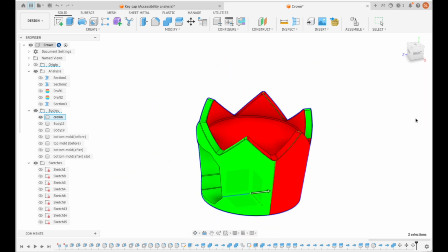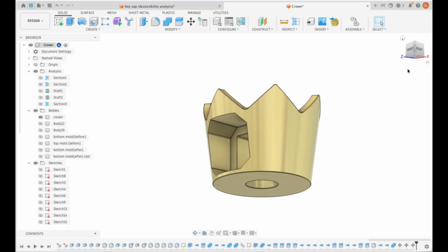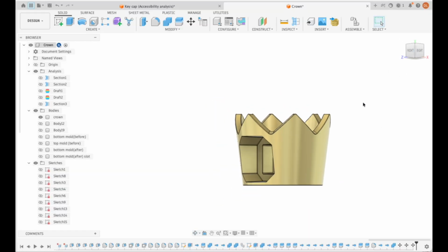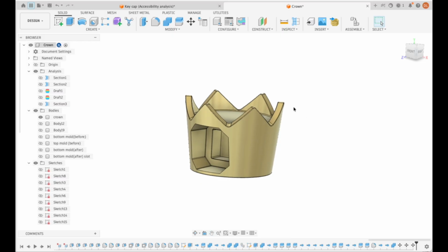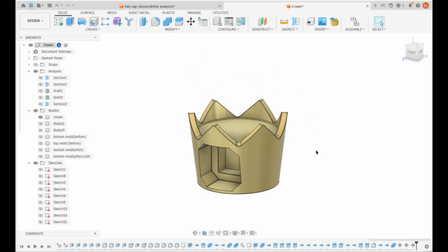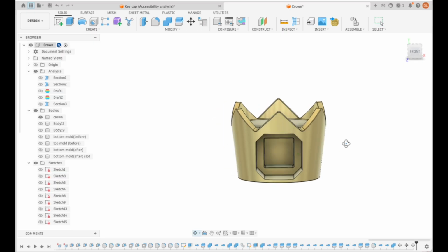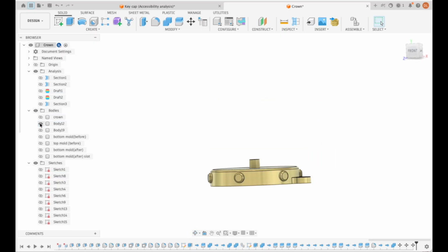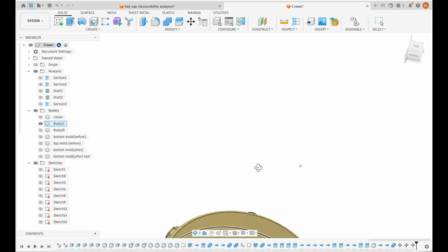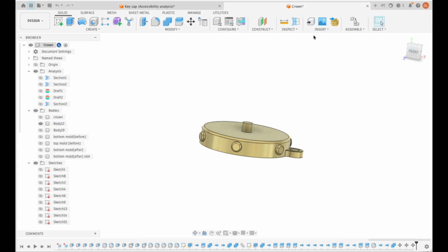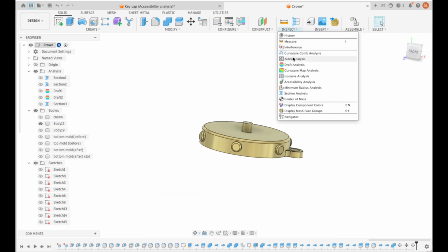This part inherently needs basically a 3-part mold, which will increase the manufacturing costs. So it might be better to improve this design for injection molding to remove the part or mold needed to produce this part, because for this single part you need a 3-part mold, or you can use different manufacturing techniques such as additive manufacturing. And for example, if we are producing this part, then it is highly likely that it might be able to be created using a 2-part mold.